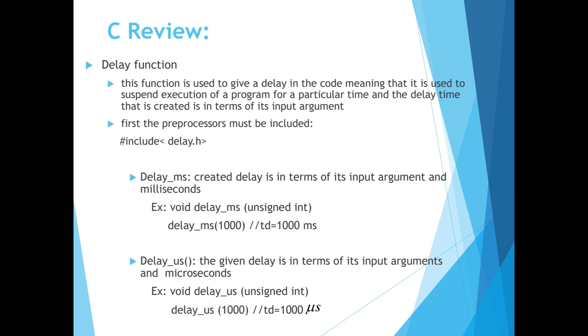But for using a standard library function, at first we need the preprocessor, which includes the header file related to it. This is a preprocessor because it starts with a number sign and include, and we have a header file related to that. The header file of the delay function is delay.h. If you don't write this preprocessor, then your code will have an error or problem.